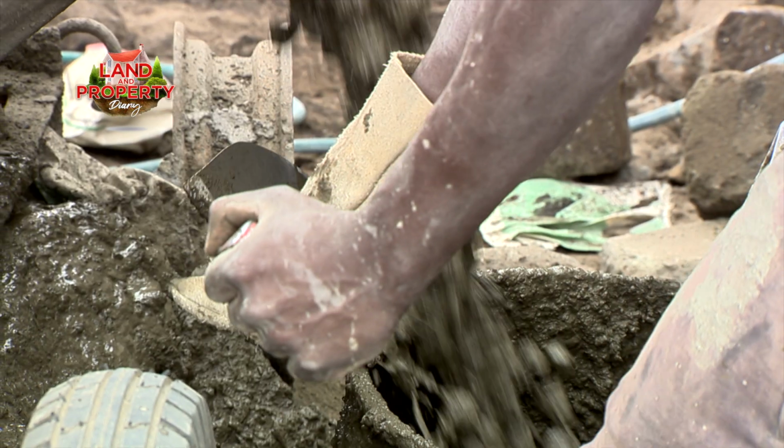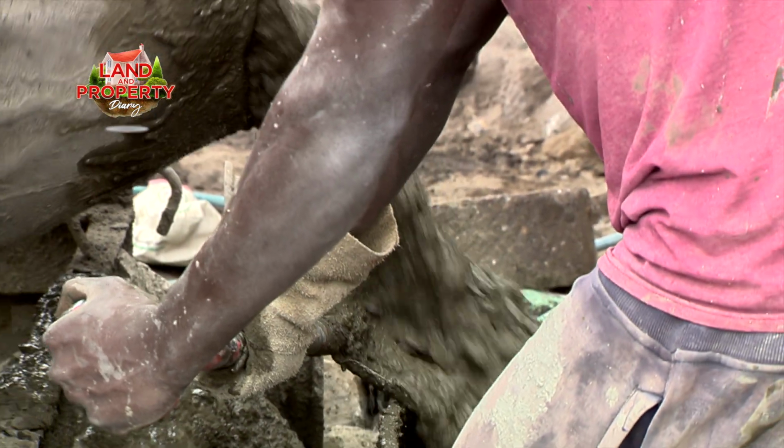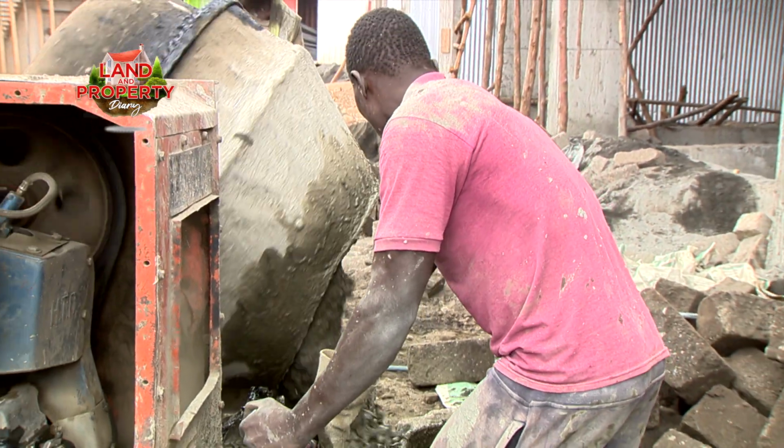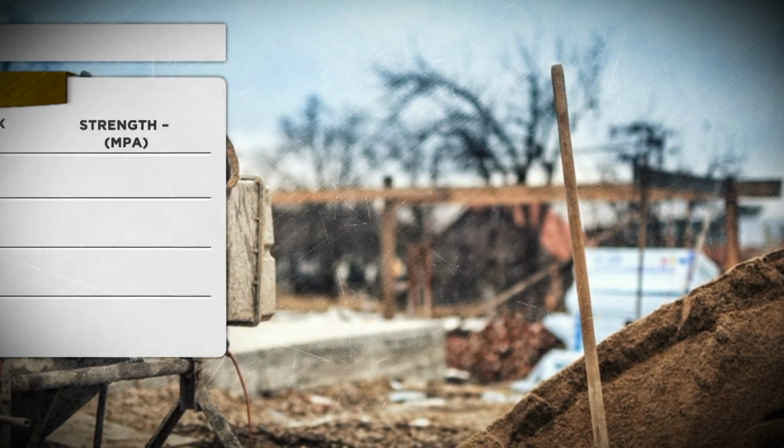The class simply means the strength acquired by this mix at the age of 28 days, in terms of newtons per millimeter squared. It's called compressive strength. After 28 days, it is deemed that a mix of concrete has acquired more than 99% of its strength. What recommendations do you give for the different ratios, for the different scenarios? When we come to classifying or grading concrete, we have classes, for example, from class 10 to even class 60.